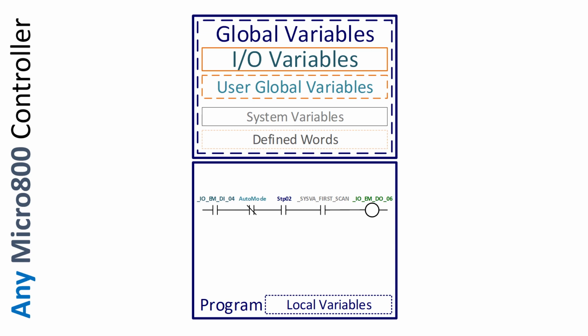And let's say it's on when there's an object in front of the photo eye. And let's say when there's no object in front of it, it's not blocked, then it's off. You don't want to put something in that spot if there's something already there. But if there's nothing there, then you want to put something there. So you need true if on and true if off, especially like the auto mode. This says if you're not in the auto mode, well, if you're not in the auto mode, then you don't want to execute this logic that's going to turn on output 6.